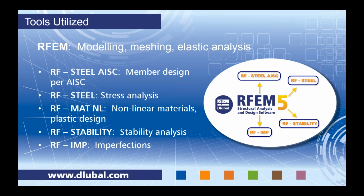For those of you that are not familiar with our program and how it's set up, I just want to briefly explain this. RFEM is our main program, and that's showcased right over here in this picture. This is where all of your modeling, your loading, your finite element meshing, and then we can perform an elastic analysis. This is all done within RFEM. Then we work on the add-on modules, and for instance, RF Steel AISC is an add-on module for member design per AISC code. We really won't be spending any time in this code today, but it's fairly self-explanatory when you're looking at our other codes that we will visit today.